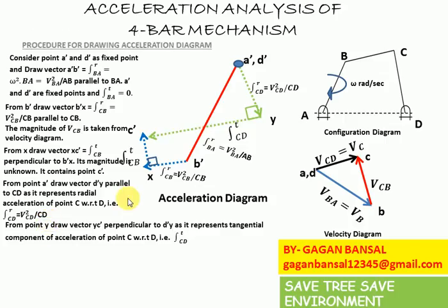From point Y draw vector Y C dash, which is perpendicular to D dash Y, and it represents the tangential component of acceleration of C with respect to D.